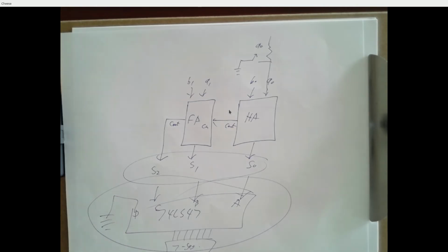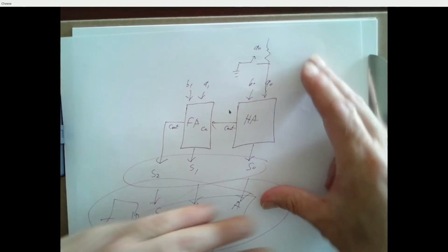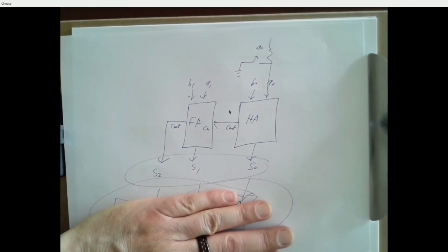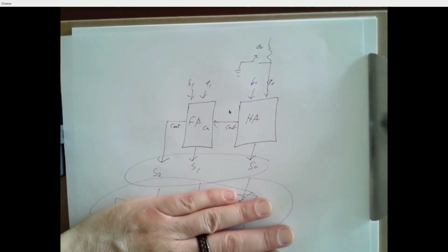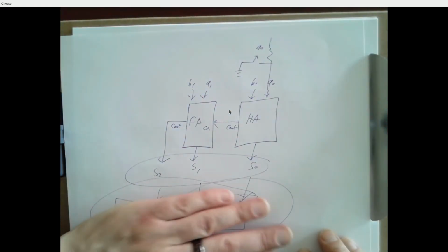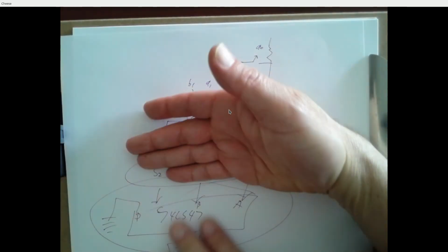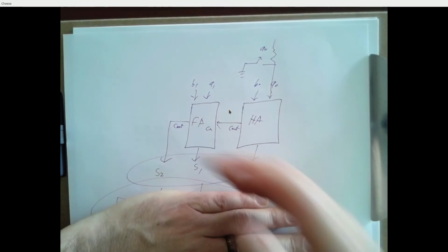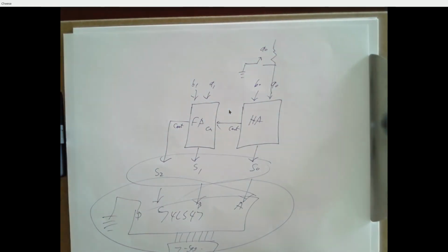And then you can build this adder and forget about all of this stuff. Just pop 3 LEDs on there, right? And add 2 and 3 and make sure your output says 1, 0, 1. And then add 2 and 2 and make sure it says 1, 0, 0. And get this whole adder part working correctly. Now you've done some work with this piece, right? And now you got this piece working. And once those two work, now you just put them together.